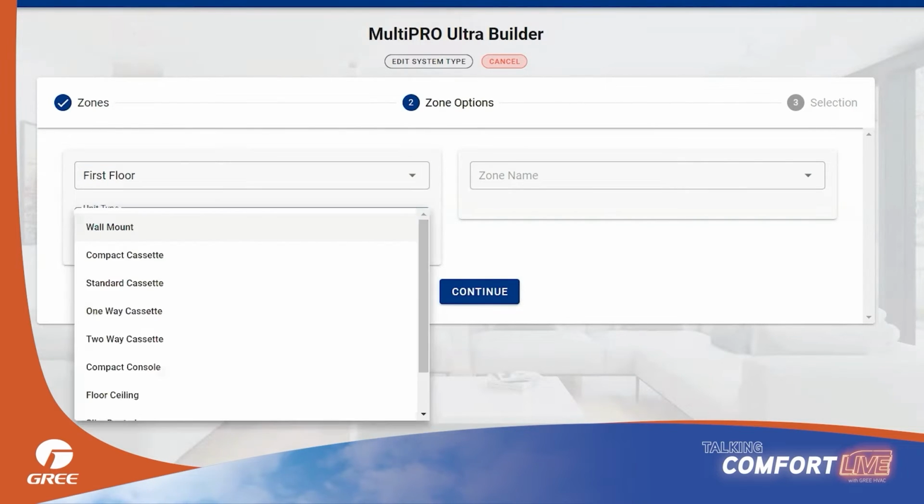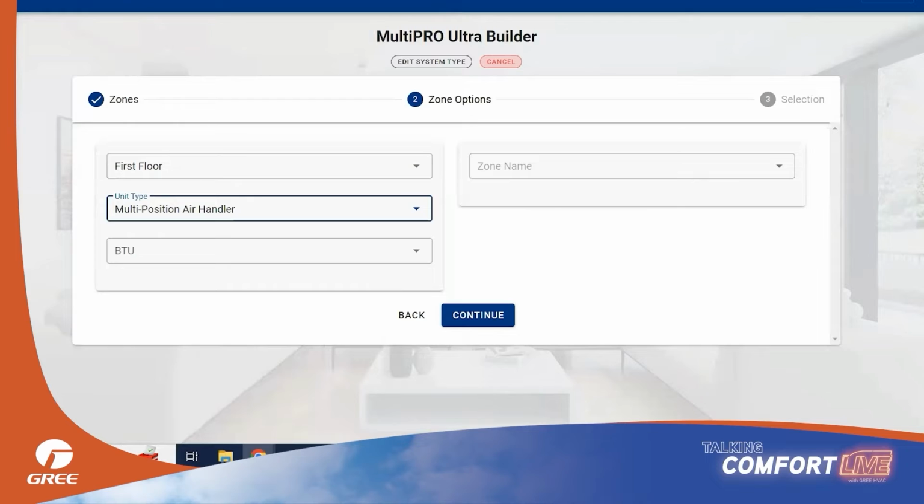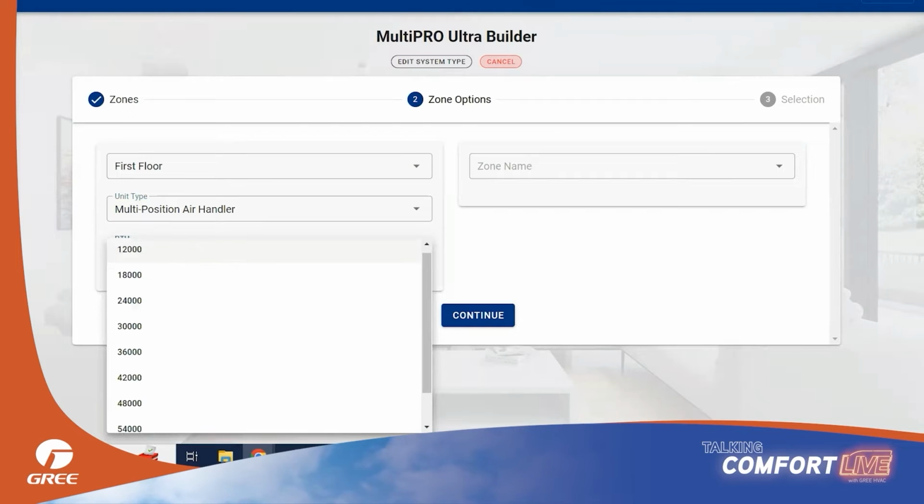Next, we're going to select our unit type. In the case of doing an entire floor, normally what we're looking at is some kind of ducted unit or an air handler. In this case, we want to select a multi-position air handler. It's based on the customer or your requirements. We know what BTU capacity we have to have because we do a heat load calculation or heat loss calculation on these projects. So we're going to select this drop-down menu that shows all the capacities that are available with the multi-position air handler.